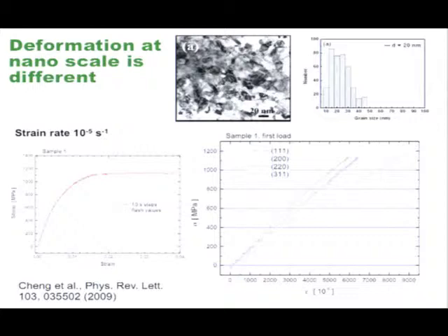No, actually, it's more complicated than that because these are time of flight, right? So you have to fold a Gaussian or Lorentzian with the intrinsic pulse shape, and then you deconvolute from that. The way Thomas did it is he assumes a model and then tries to fold it with the instrument resolution to match the diffraction pattern. Mm-hmm. But in any case, remember that linking the strain that you measure with the stress that you want to know is the big business.